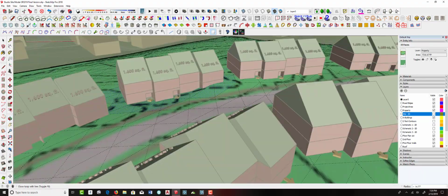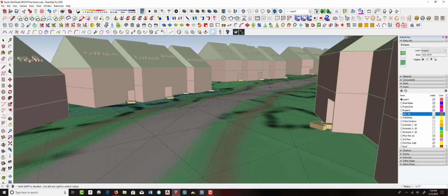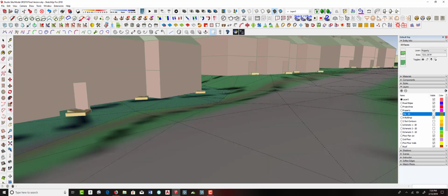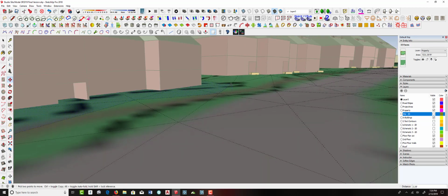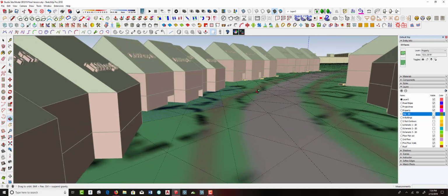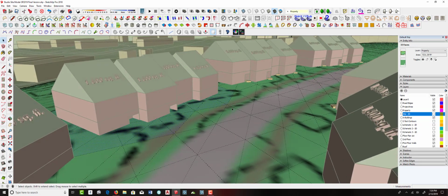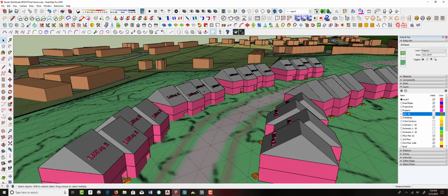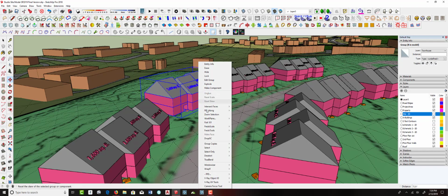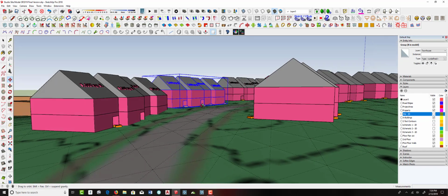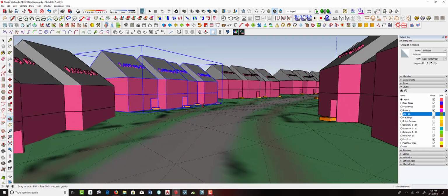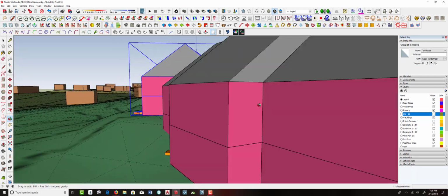All right, and let's do Make Planar, XY. Okay. All right, again, now you can see this is maybe a little low. We'll hit Move, bring that up a little bit. So it's a little lower than the last group, but not completely lower. And that looks pretty good. Get out of the group, select this, move it up, right click, drop GC, puts it right down on that platform. So again, you can start seeing how this is going to be working up.